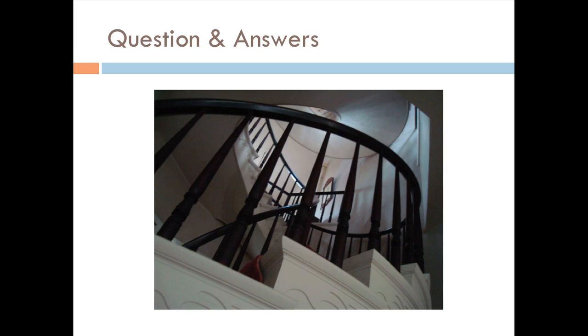So it gives a place for that water to expand. Limes tend to do that better because they have an open pore structure. Cement tends to have a very closed pore structure. The pores are not interconnected. So it's porous, but the amount of pores that interlock is not nearly as great. I hope that answers the question, or attempts to.